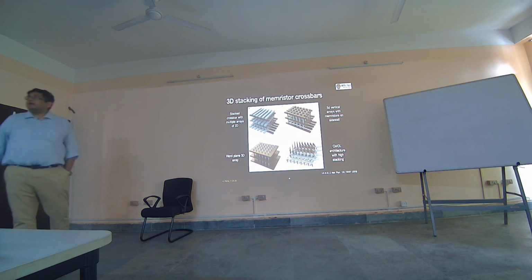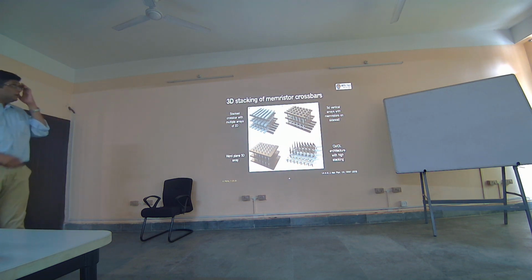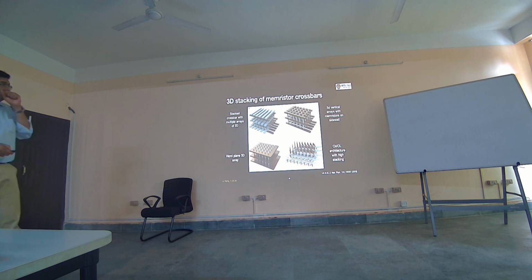There are different ways of making these resistors. The simple way, as I said, is using these 2D arrays where you have one metal running this way, that metal running the other way, and then stick an insulator between them. You can also think of it where we build the memristors along the finger, and essentially have two electrodes, so one you put here, the other on top, and a filler between, which conducts the memristor.